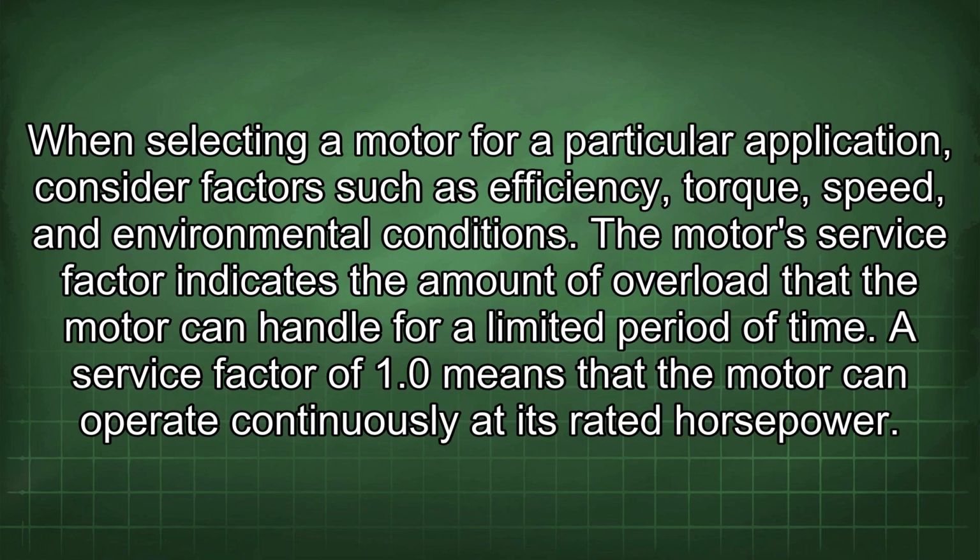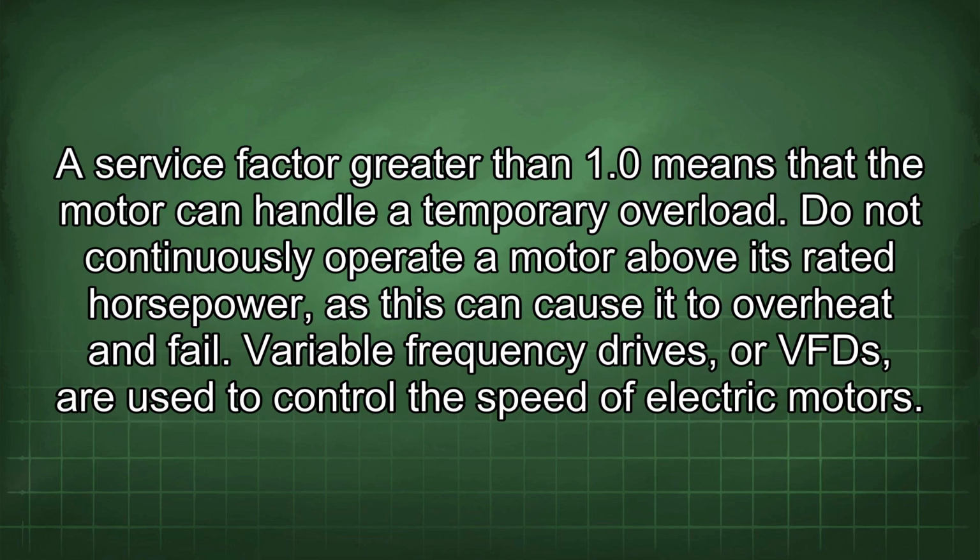When selecting a motor for a particular application, consider factors such as efficiency, torque, speed, and environmental conditions. The motor's service factor indicates the amount of overload that the motor can handle for a limited period of time. A service factor of 1.0 means that the motor can operate continuously at its rated horsepower. A service factor greater than 1.0 means that the motor can handle a temporary overload. Do not continuously operate a motor above its rated horsepower, as this can cause it to overheat and fail.